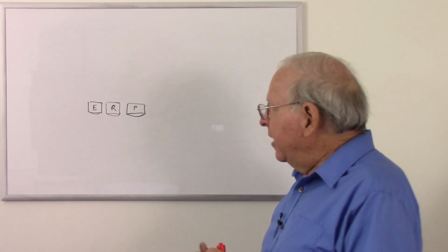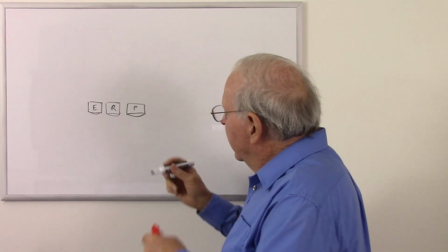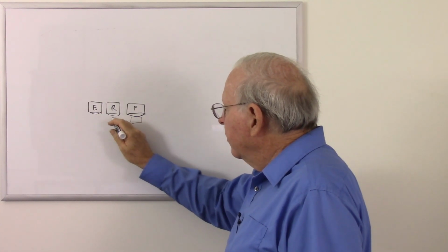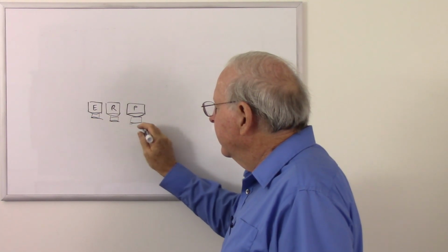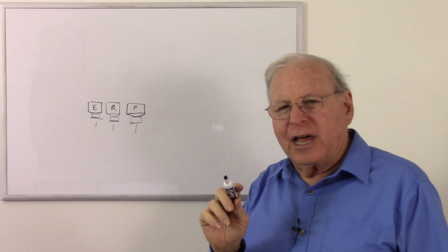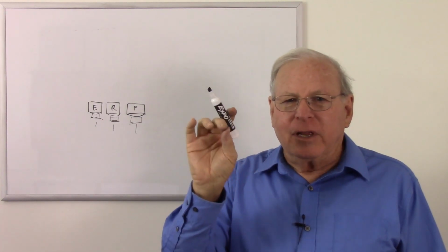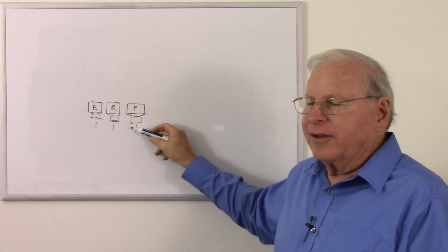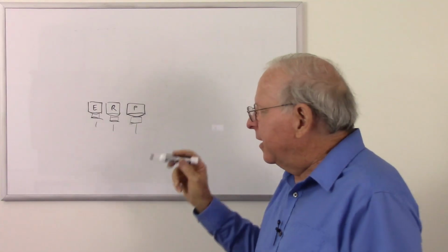A little more about the heads. You also might find that your heads are advertised as parabolic. So if we have cylindrical heads like these, we required pressure pads, little felt pads on springy arms that pushed the tape against the head. And that's the problem, because that pressure pad becomes unaligned or worn or whatever. If you don't have that tape held tight against the head, we lose that high frequency response. And so that was a perennial problem, always having to replace these pads, cleaning them sometimes. Sometimes I'd have to take a little needle and kind of pick at them to kind of fluff them up a little bit to get the pressure right.